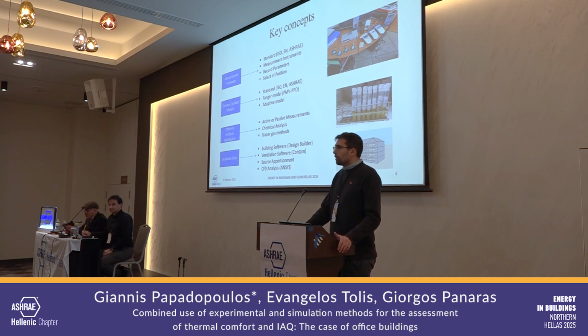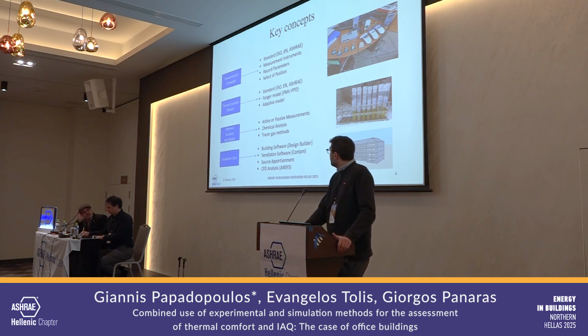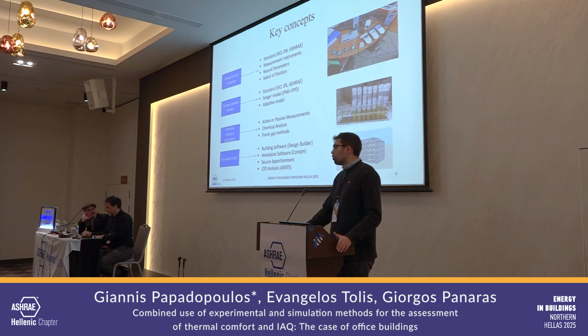So this whole measurement campaign is based on international standards like ISO or ASHRAE, as well as the time interval we choose to record the parameters inside the building. The selection of the position of our instruments is very critical. For example, we put them not very close to windows or sources of heat energy.